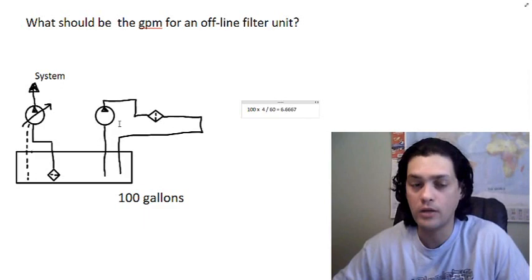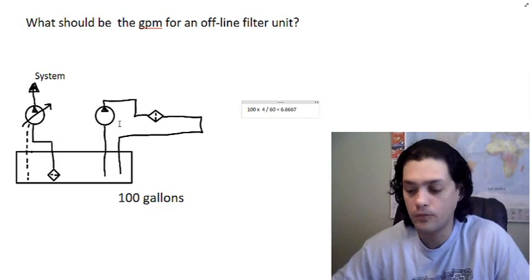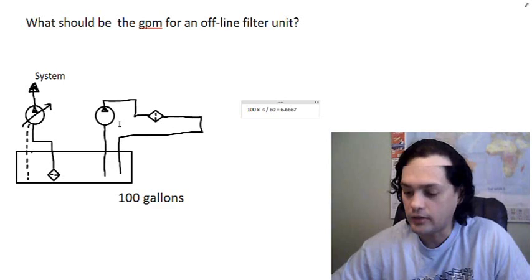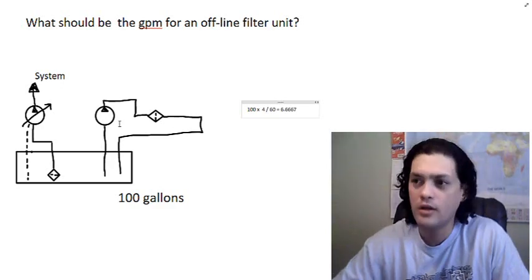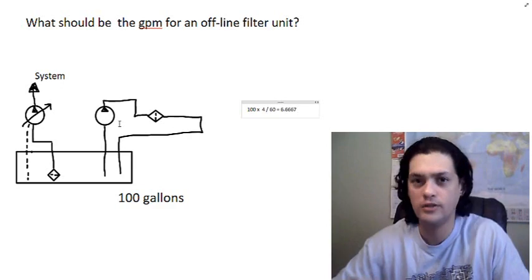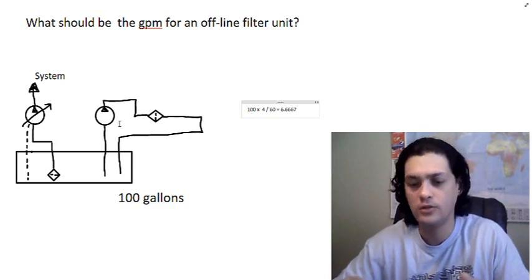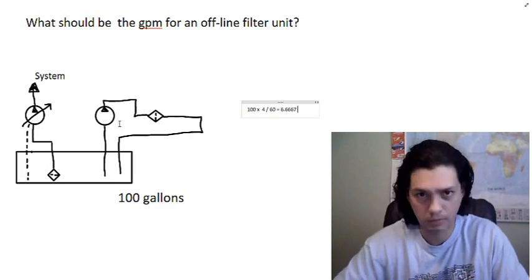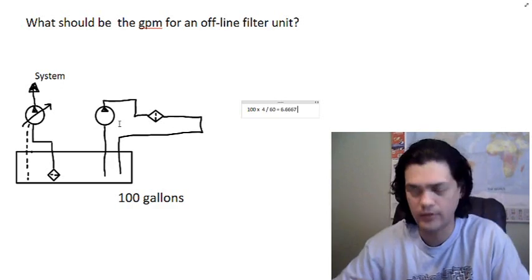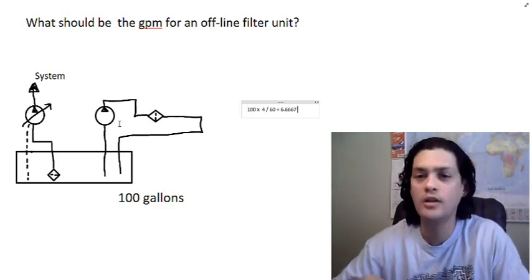For example, a lot of people put a machine in and they see, for example, a directional control valve, the solenoids. The solenoid keeps burning. You have to change solenoids every so often. One reason why a solenoid may be burning in your system after a while is because contamination also accumulates between the spool and the wall of the valve.